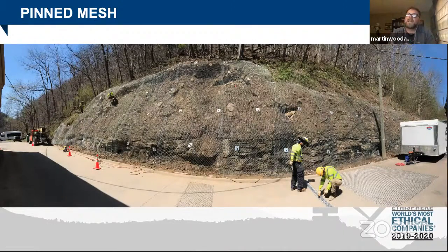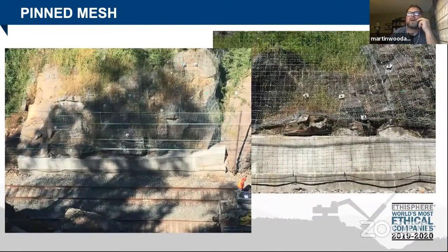In that particular case, what we do is we come in and put in these pins, and they go through the mesh, and then the plates go down and cinch it up. What it does is it contains, or tries to contain, everything into that slope. It doesn't stop any of the weathering processes. But it significantly minimizes that maintenance and how fast that maintenance is, and it gets rid of that catchment area that you need. But you can imagine that erosion is still going to happen in this type of product, and you will have to have maintenance in the future. But it's the next step up if you don't have a catchment area.